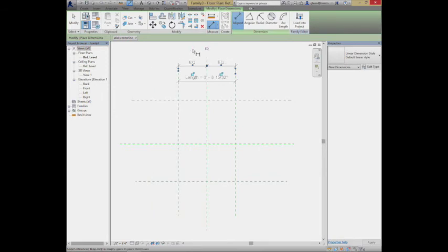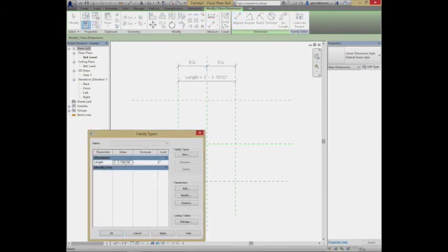And what's that all about? All I'm trying to do is, as I go through and enter a dimension in here, like 8 feet, always make sure that it goes to either side. So two things. Go ahead and get the length parameter the way you want it, but also get the equality in there. That way it sort of stays centered on what you like.